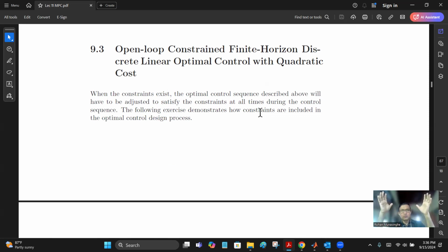When you reduce your cost, you cannot go to the global minimum if there are constraints that will restrict you. Suppose there is a situation, if you get a very big control action immediately at the beginning, you can control it quickly so that your control time reduces, so your energy reduces. Okay. But unfortunately, that is not possible if you have a certain limit for the control signal.